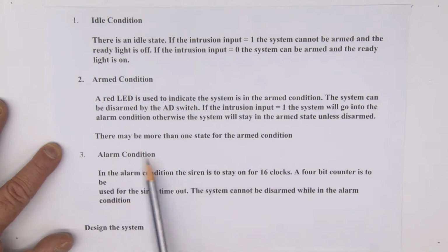All right, alarm condition. In the alarm condition, the siren is to stay on for 16 clocks, and a 4-bit counter is going to be used for the siren timeout. The system cannot be disarmed while in the siren state or the alarm state. So our task is really to design this system.